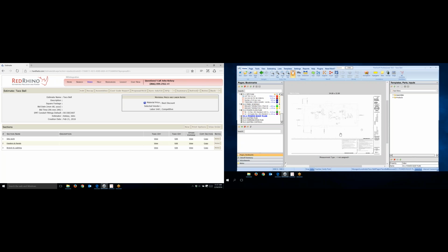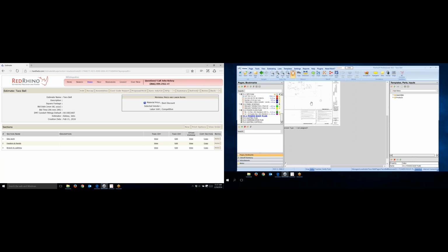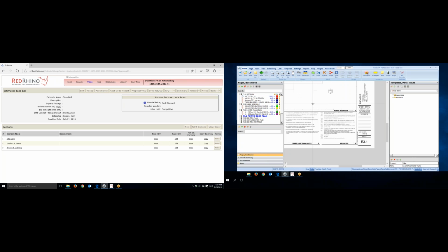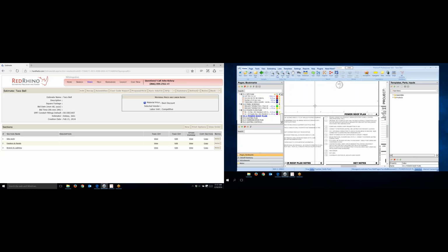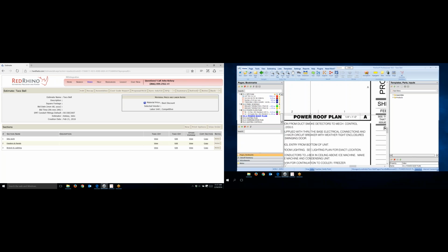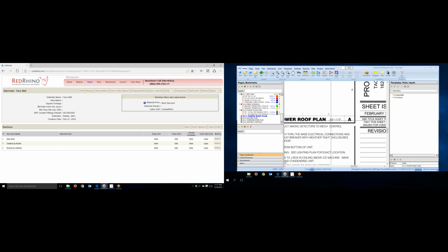So I'm going to pan and zoom to find out what the scale is and show you how that works. Now I just click on pan again, and it stops panning. Now I'm going to see what the scale is. So I'm going to systematically move the plans over here and then zoom in. And what I'm looking for is to show you this. I already know it, but it shows here that the plans' scale is 1/4 inch to 1 foot.